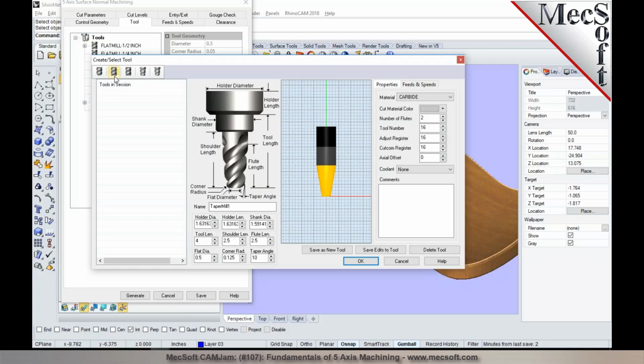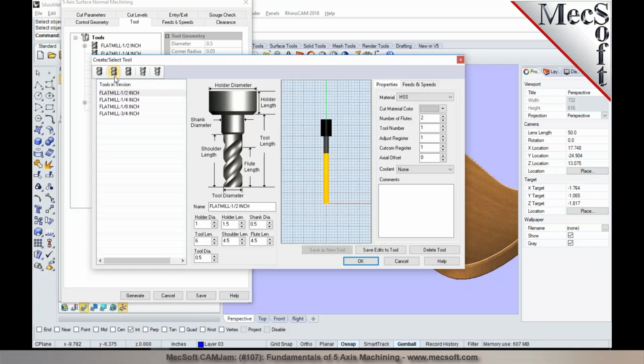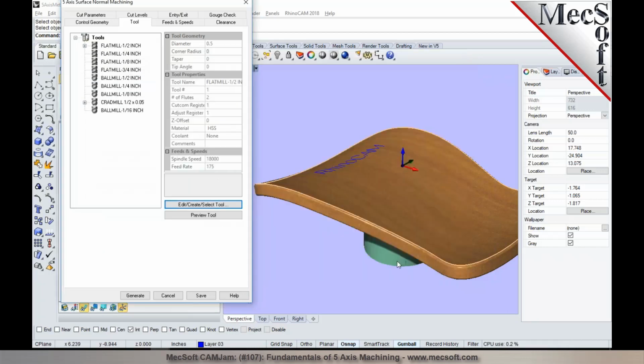And defining your tool and saving the tools to your library works very similar to how you've done in your 2, 3, and 4-axis methods. And if you're using a gauge length, this is where you specify the tool length, which is the distance from the tip to the spindle face. And we add that information to establish the total gauge length for machines that have a rotary head and if you're outputting in the world coordinate system.